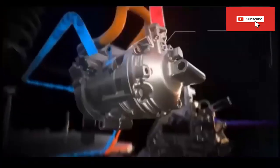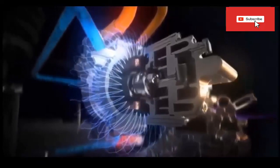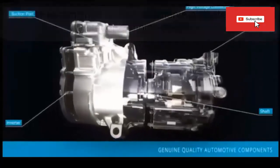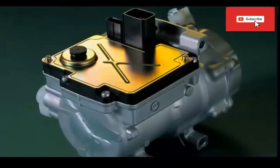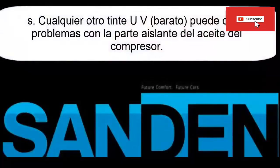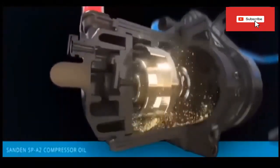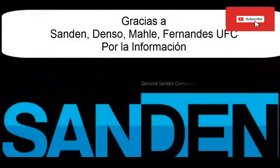The type of oil used in an electric automotive compressor generally differs from the oil used in mechanically driven compressors. The highly insulating oils are recommended to protect the electric motor. If you use the wrong oil, it may cause a short circuit and destroy the electric motor of the compressor. If you use a UV dye, be sure to use the correct SAE-approved type of dye. Any other cheap UV dye can create problems with the insulating part of the compressor oil. Like self-powered electric compressors, they are hermetically sealed, there is no shaft seal, and no potential risk of refrigerant leaking into the outside air.